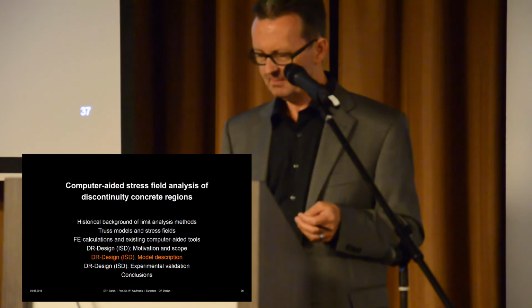Okay, so maybe some more details about the model. This is a quite central part of the reinforced element: horizontal and vertical direction reinforcement, with the concrete stresses in compression and tensile stresses. Now the question is, how would you calculate these? On the right side, you can see a tension cord, shown here for the vertical reinforcement.